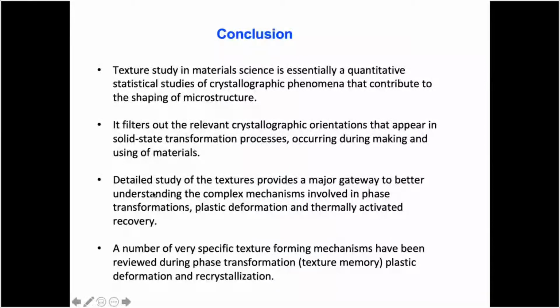In my third conclusion, I reiterate that detailed study of the texture provides a major gateway to a better understanding of the complex mechanisms involved in various phenomena, such as phase transformation, plastic deformation, recrystallization. And then I've backed up my story with a number of typical examples in which the knowledge of texture can help us to obtain metal sheet with better mechanical properties.